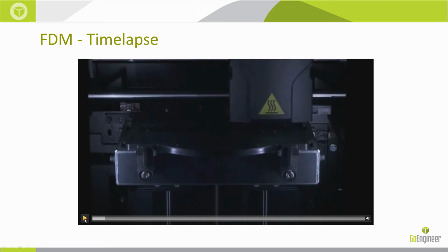So I have a quick video here to demonstrate what's going on. This is the view into, I believe it's a Uprint SE Plus. It may be a Fortus 250. It's a Uprint SE Plus. We have our build tray, which is a black tray. That's what we print on. At this point, we've started the print. It's taken us less than 5 minutes to process our STL file for printing and send it over to the machine. The machine, if we've recently changed the material, has done a self-calibration. There's no calibration on my part as the operator. And we start our print.